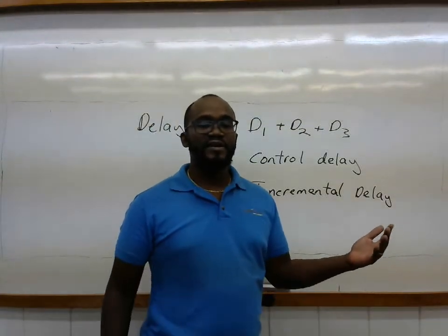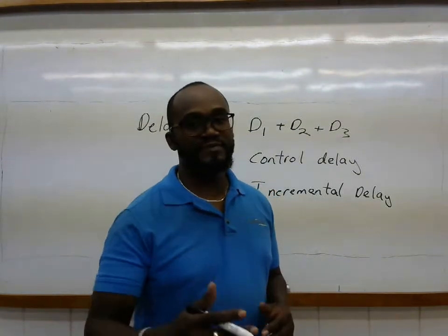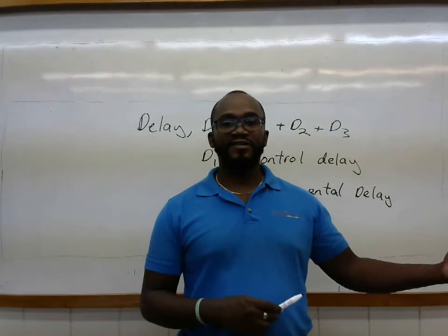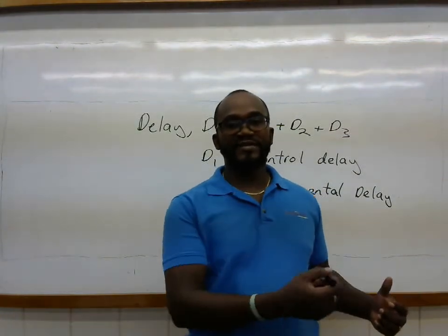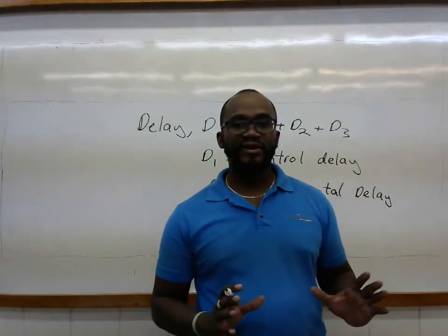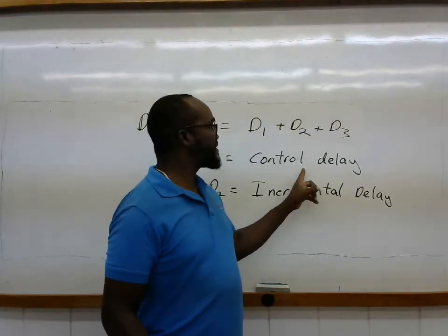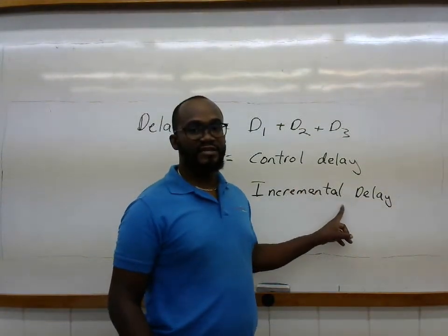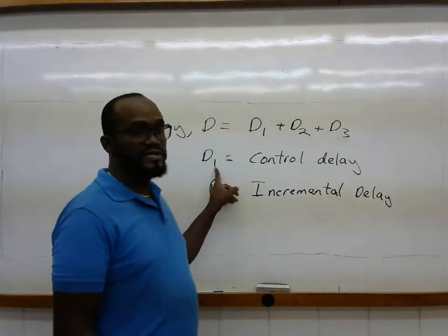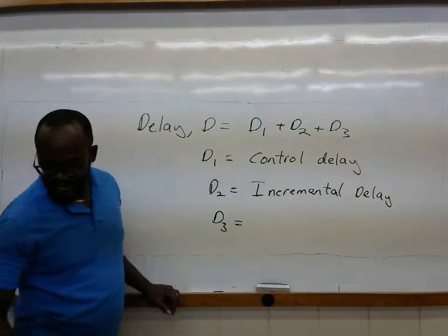For example, you may be in a fairly tight grid within a city or along an expressway where you have a series of signals, and because of the effects of signals upstream, the traffic stream is interrupted and the arrivals appear fairly disjointed or not in a platoon, so that this causes an additional delay outside of the control delay at that particular intersection. So that is what the D2 term represents in addition to D1.